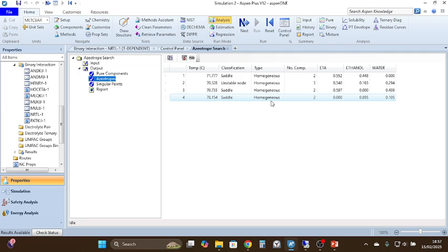You can't differentiate the components with your naked eye. If you look at a container that has all these three components, they will appear as a single liquid. But in the case of a heterogeneous azeotrope, they lead to a phase separation which you can see. Either some vapor might be formed on the surface of the liquid, or two liquid phases will be formed, something like that. So it becomes a heterogeneous azeotrope.